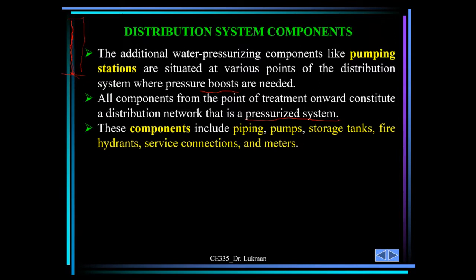And of course, we have other components like the valves. The valves are very important. Okay, we call them pipe appurtenances, the valves, the connectors, and all that. Because there are valves installed at intervals to ensure that the water flows in one direction. Okay, you need to ensure unidirectional flow of water, and there are ones for when there is need to take a particular pipe out of service for maintenance or any repair work. So there are different types of valves that serve different purposes.